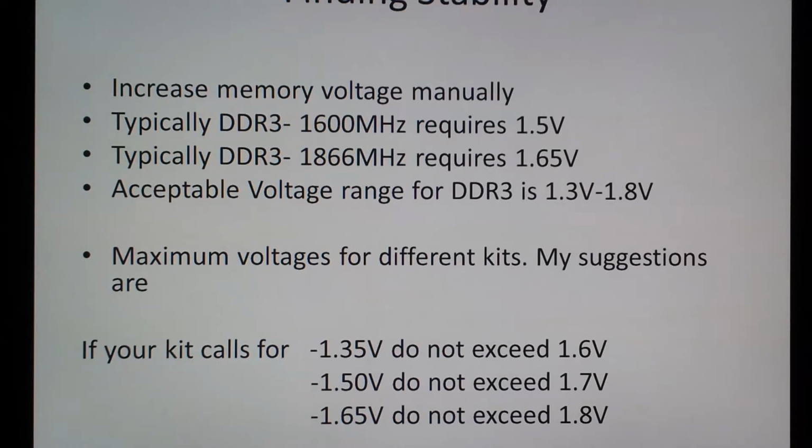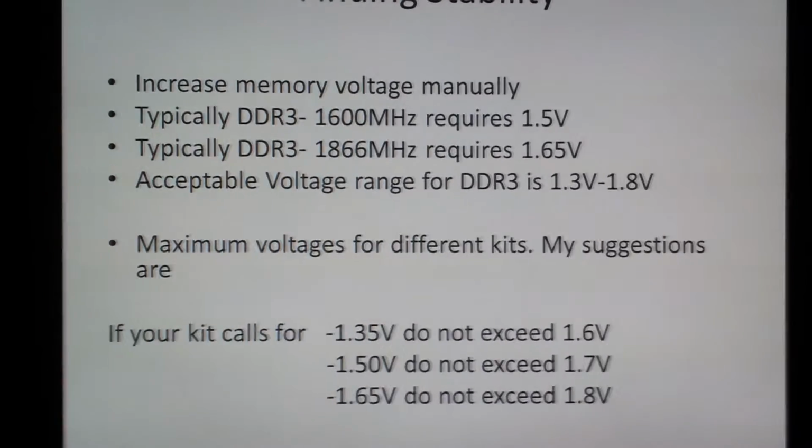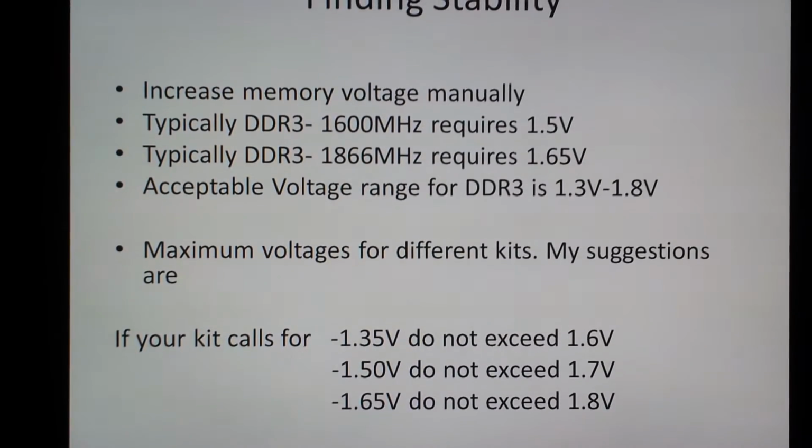Okay, so basically finding stability. Now, there are a lot of different memory kits out there, so this is a very, very difficult subject to talk about. So I'm going to try to break it up as best as I can in terms of what are acceptable voltages for DDR3 memory. Now, typically, DDR3 memory at 1600 megahertz requires 1.5 volts as a JEDEC standard.